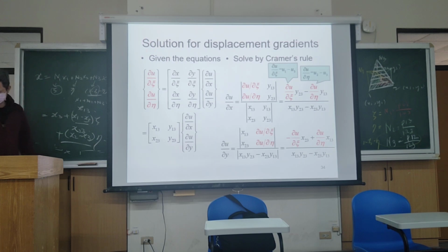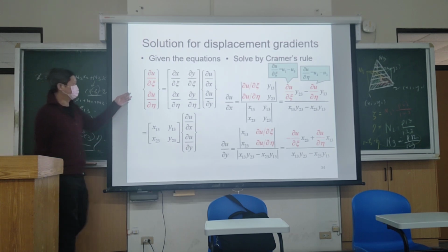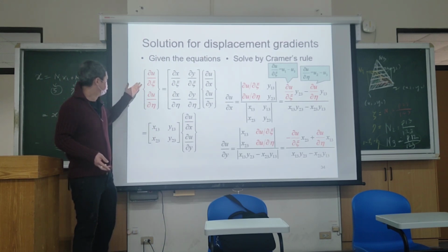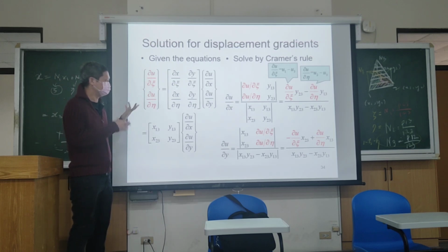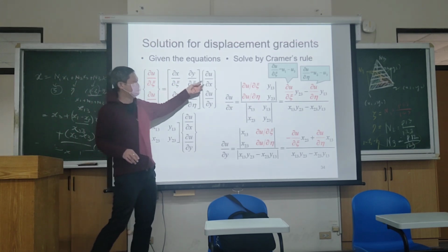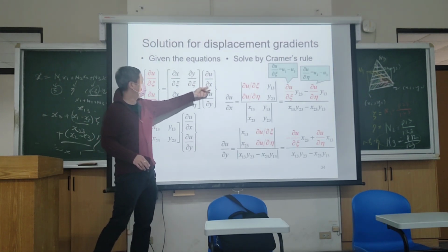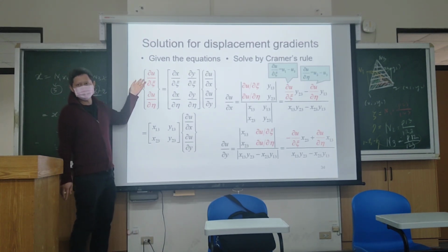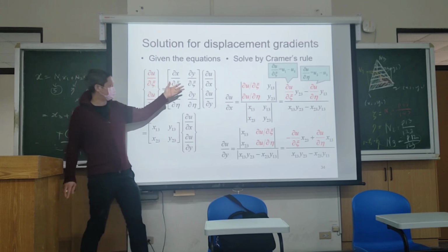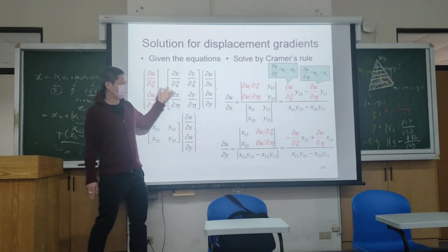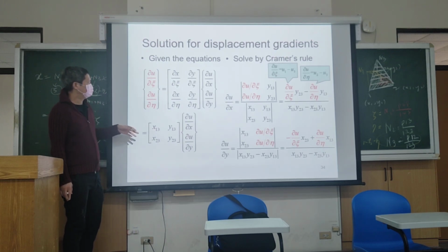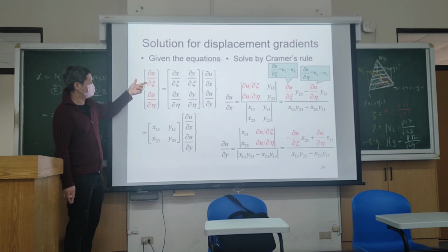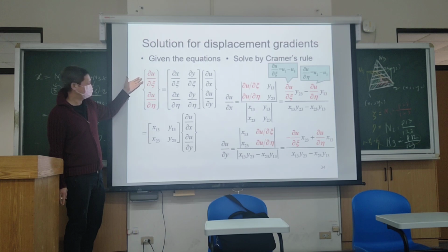So finally, we are not stopping at the natural gradient because you can't use the natural gradient to calculate the strain energy. Okay? This natural strain won't be useful. So what you need now is to find the del u del x and del u del y. To find this, you are applying the identity between natural coordinate and physical coordinate linked up by the Jacobian. Okay? And you can take the derivative of the u with respect to the coordinate. This is an obtainable value.